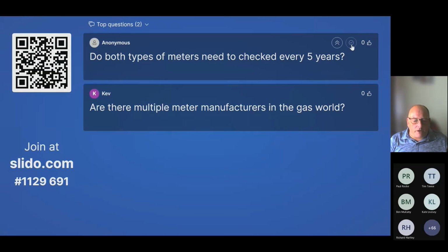They removed that with the introduction of smart, and the fact that they knew that most organisations were going to be going in and changing them, and that meter reading was becoming less and less of an activity because it will be done remotely. The other advantage is that with the data they could get off smart meters, they should know quicker that there was an issue on site. So they did remove some of those obligations. However, not all organisations stopped doing those checks. But when it comes to checks for that type of activity, that's a legal obligation, is the 5 years.